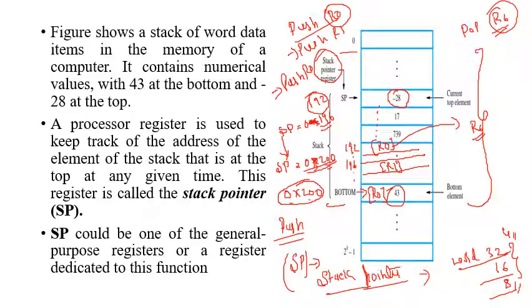I can use any register irrespective of what I have pushed. For example, if I have used the instruction push R0, I need not use pop R0. I can use any register. The only difference is the data present in the particular address pointed by stack pointer will be retrieved back in whichever register you have named next to the mnemonic.